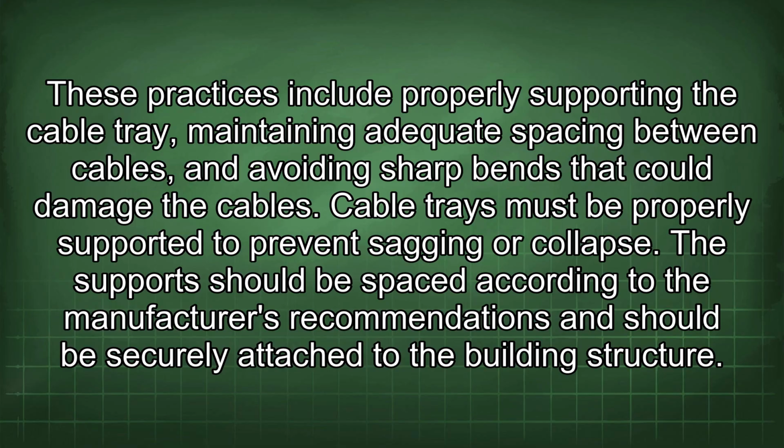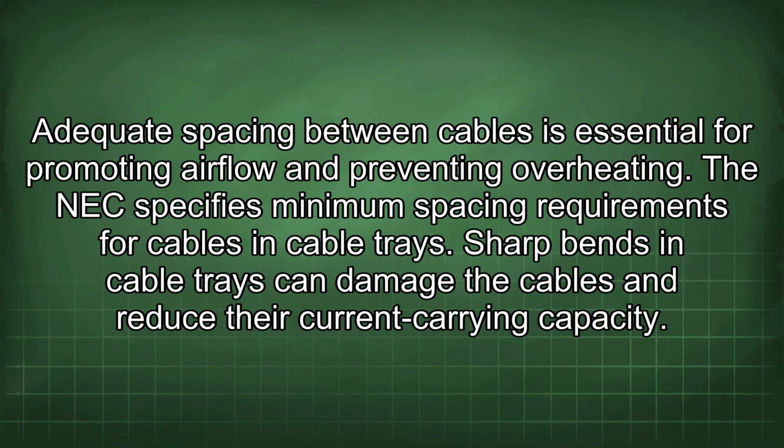The support should be spaced according to the manufacturer's recommendations and should be securely attached to the building structure. Adequate spacing between cables is essential for promoting airflow and preventing overheating. The NEC specifies minimum spacing requirements for cables in cable trays.